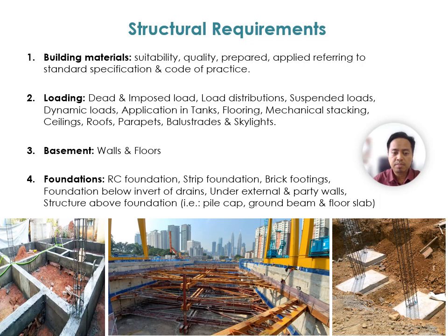Thirdly, the basement, with specific requirements on the walls and also the floors. Number 4 is the foundation. It tells engineers to design the RC foundation, strip foundation, brick footings, foundation below invert of drains, under external and party walls, and structure above foundation, for example pile cap, ground beam and floor slab. The photo below shows the foundation works that are commonly constructed in Malaysia.